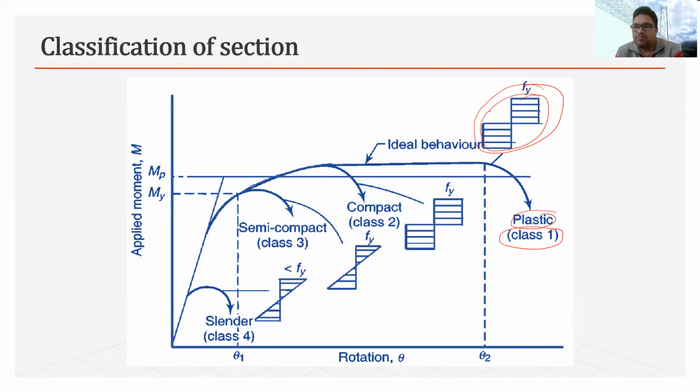So the beam will experience maximum stress, plastification is occurring, and because of that, a hinge is also forming. So this is the ideal failure that we want in our section. If the I section is experiencing full plastification, or if it is able to achieve the maximum plastic moment because of the load, we will classify that section as class 1.